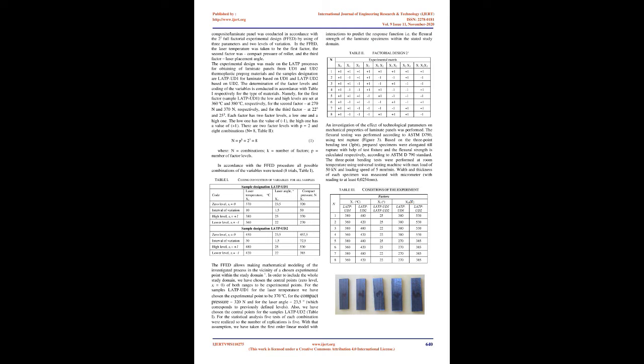The head is attached to a robot arm, as shown in Fig. 2. The tape head consists of a consolidation roller with an outer diameter of 90 mm, a tape feed, guidance, tensioning, and cutting system for UD prepreg tape, an optic lens connected via a fiber optic cable to a remotely located 3 kW diode laser heat source, and a temperature sensor, a pyrometer. A tape placement process involves pulling of the thermoplastic prepreg tape from a spool through the feed and guide assembly. On the way to the consolidation roller, the tape is heated to a temperature based on the type of polymer, using a laser. The tape is then placed on the tool and consolidated with a roller.